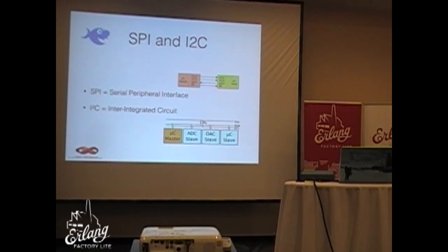And there is also a clock line that determines when data goes in and out. So chips have specifications of when they are reading and writing, and then you have to basically sync to that clock and figure out when you should read or write from one of these components. And there is also a chip select line that you can use to chain even more chips on the same line, and then use this to drive which chip gets to read and write on the same line.